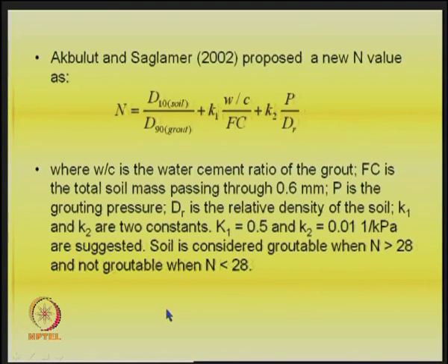But then some more people have been working on these lines, particularly when you try to do a very big project. Say for example, there is a big dam, an earth dam coming, or some rock-filled dam or whatever dam is coming up, then the foundation should be stable, there should not be seepage in the foundation, there should not be bearing capacity failures in the foundation and all that. How do you handle that? That is only possible if you have a proper understanding of the pore size, the grout size and some of this information.